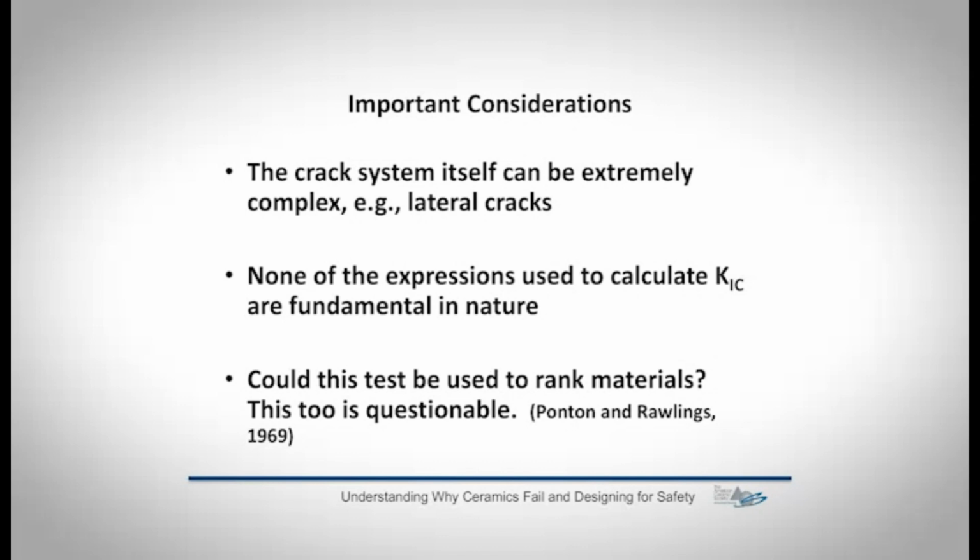As I mentioned at the beginning, none of the expressions used to calculate fracture toughness are fundamental in nature. They're derived in various ways, and they differ from one another. And so you think, well, can I use a test to rank materials? And there's an interesting article by Ponton and Rawlings, and I show their reference at the end, that this is also questionable, that depending on the expression you use to calculate fracture toughness from this test, you can get different rankings from one material to another.